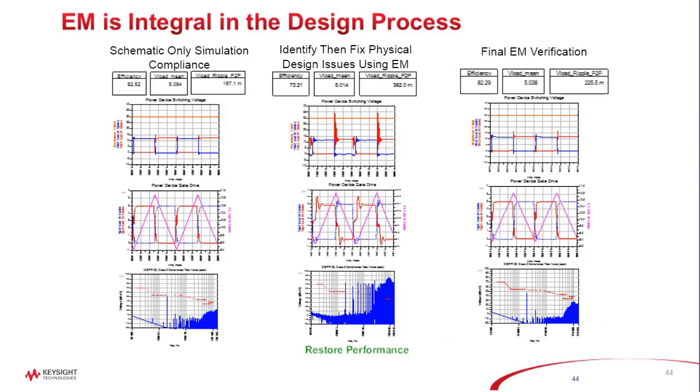Electromagnetic analysis is essential to what we're doing. The layout has to be run, the artwork has to be run through an electromagnetic solver that will extract the inherent parasitics associated with the artwork. That includes all the different layers, all the different vias, metal thicknesses, footprints for the pads, footprints and surface mount pads for the components.